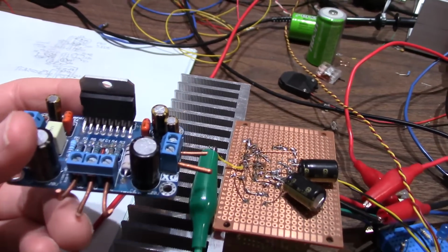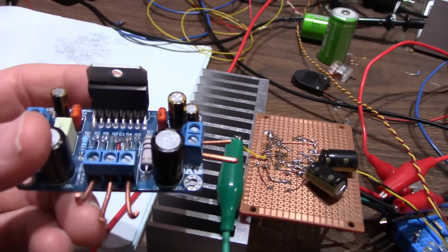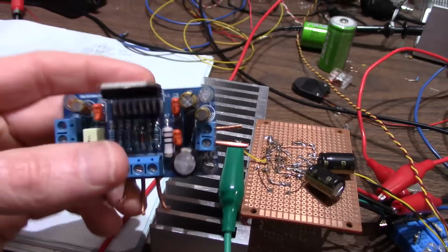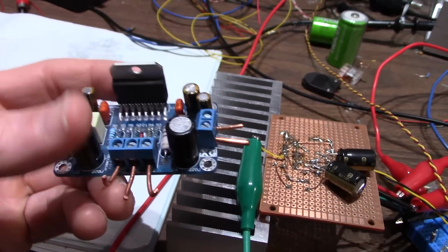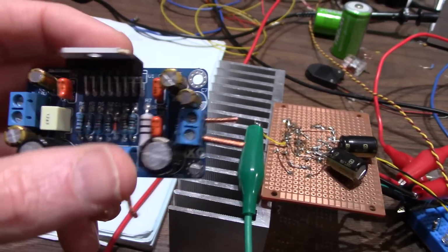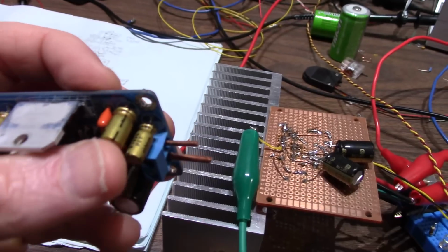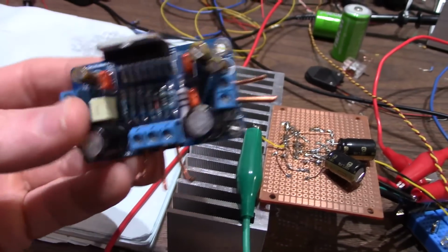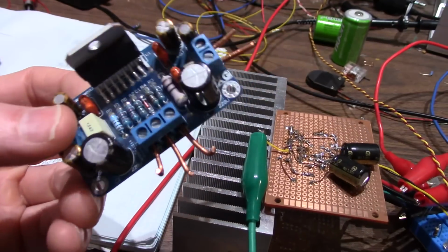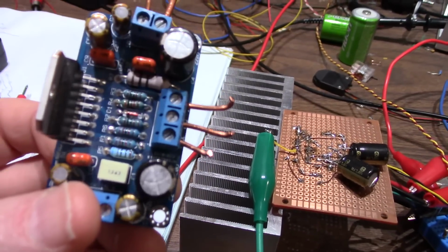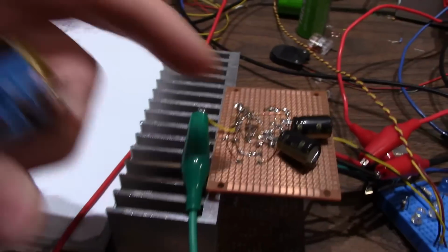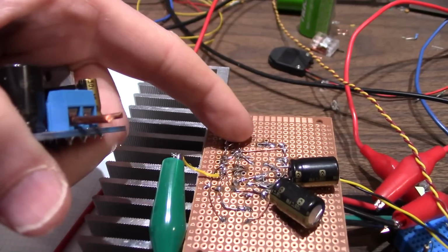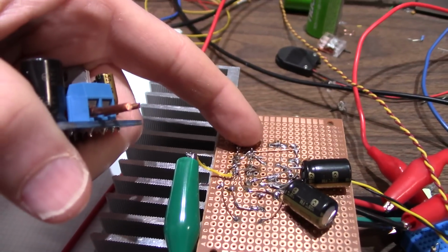So 3 comparisons. Now you can't just pop a 7294 on a 93 board because the bootstrap loader cap goes to a different pin. So I'll have to make that adjustment. And I'll need to change a resistor value so the gain's the same on my board.